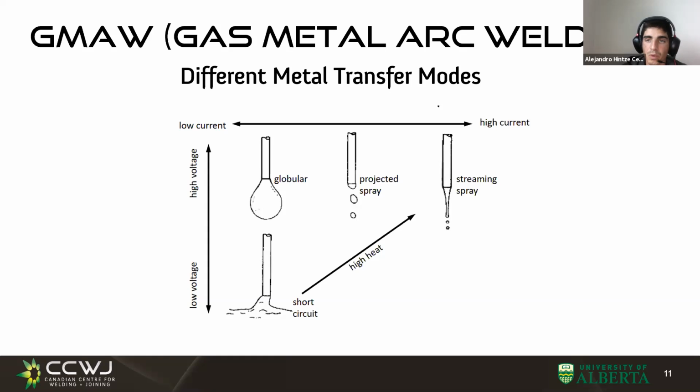and if you remember, we have what they call STT, which is short for surface tension transfer, and pulse transfer, which are different transfer modes that take advantage of having new and state-of-the-art equipment that can play with the current or the voltage waves, just to have a different type of transfer mode. But we'll see now how they look and how they sound.